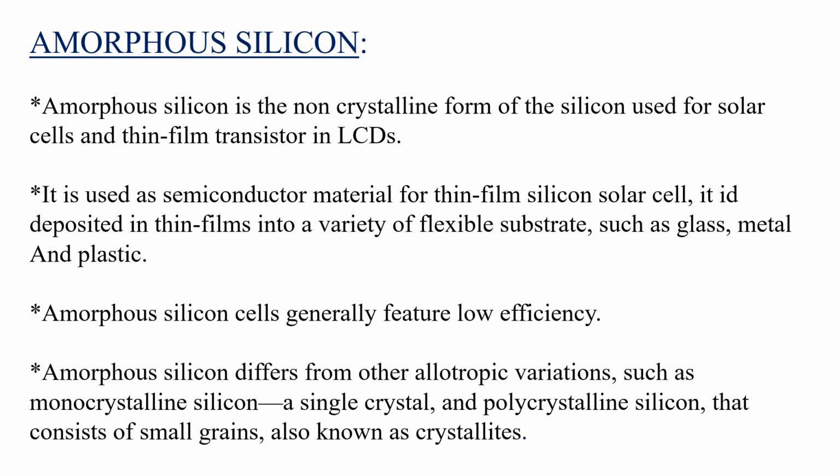One further advantage is that amorphous silicon can be deposited at very low temperature, for example as low as 75 degrees Celsius. This allows deposition on not only glass but on plastics or even on paper substrates as well, making it a candidate for a roll-to-roll processing technique. Once deposited, amorphous silicon can be doped in a fashion similar to crystalline silicon to form p-type or n-type layers and ultimately to form electronic devices.